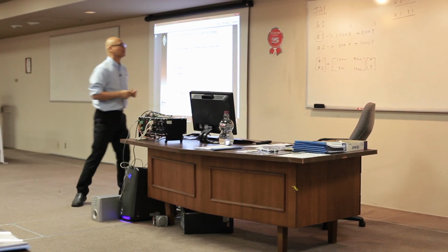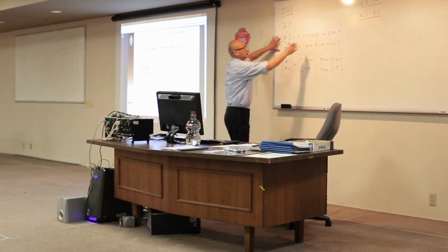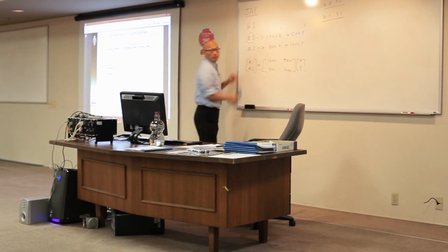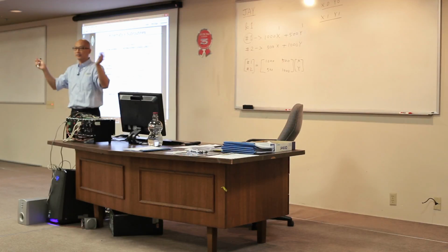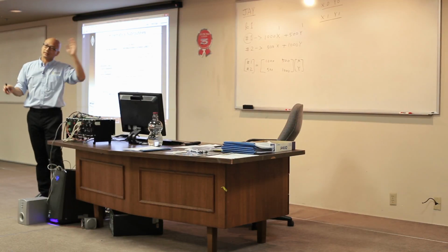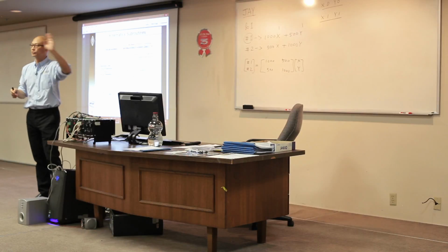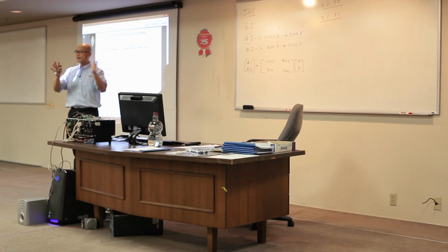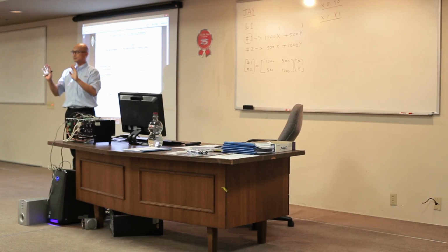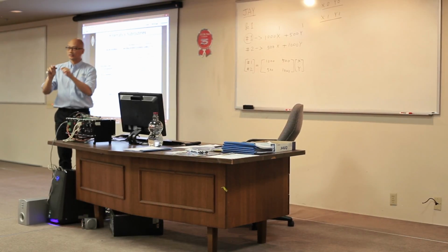Okay? Once you define the axis definition here, we actually put these variables in that matrix, and then we do the inverting of the matrix to actually calculate from motor to axis, from axis to motor. Okay? This idea should be understood right now.